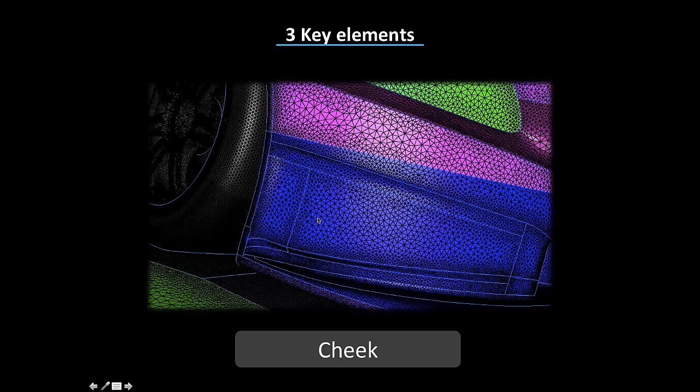So one important thing with the cheeks, and it's even with end plates on cars with front wings, is that you're trying to do a couple of things there. You're controlling drag of the car. One thing, you can see that little reflex that the mouse pointer is sitting over the top of now. It does a couple of things. It's generally kicking the flow to the outside of the wheel so that the turbulence on the wheel doesn't have too great of interaction and keeps the floor area as clear as possible underneath the car.